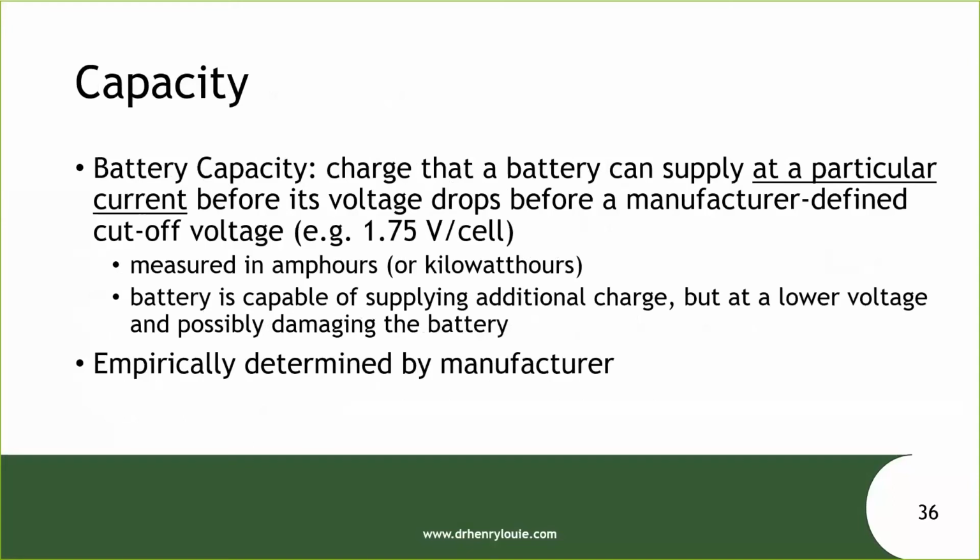So the capacity of the battery is extremely important. This is really where most of the design work goes, selecting the right battery capacity. And there's a lot of misunderstanding on how to interpret the capacity of a battery. Battery capacity is typically measured in amp hours, but sometimes you'll see it represented as kilowatt hours or approximated in kilowatt hours. And the battery capacity is determined by a manufacturer.